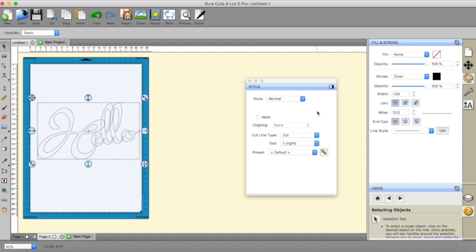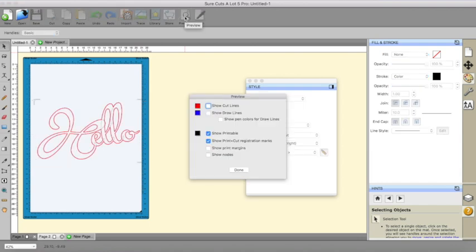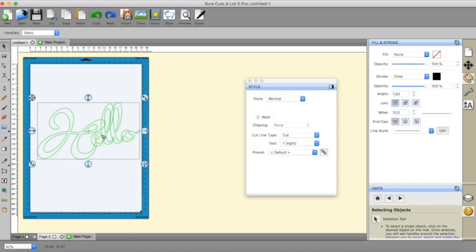But the other thing which a lot of people ignore, and it's very handy, is this weld one. Now you can see my letters. I've kept them quite deliberately. I've kept them completely and utterly separate. But if I choose the weld setting, when I go to do a cut, and if I choose a preview, you can see that the cut line is ignoring the bits where it overlaps. Again, that is one of the things that doesn't affect the file, it just does it when you cut.